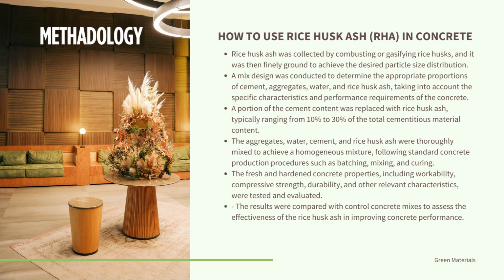So moving on, how to use rice husk ash in concrete. Rice husk ash was collected by combustion of rice husk and was finally ground to achieve the desired particle size distribution. A mix design was conducted to determine the appropriate proportion of cement, aggregates, water, and rice husk ash, taking into account specific characteristics and performance requirements of the concrete.